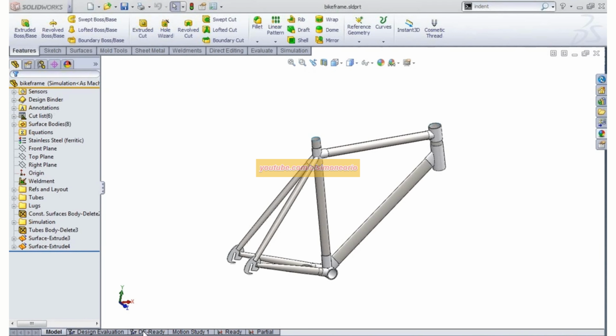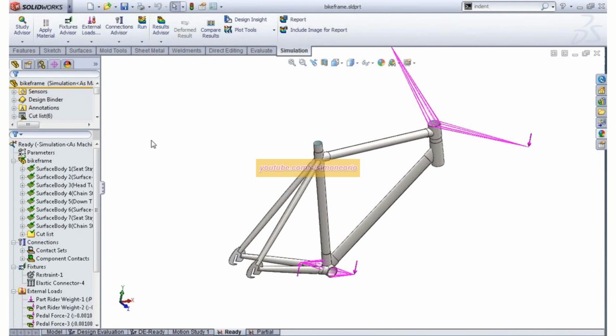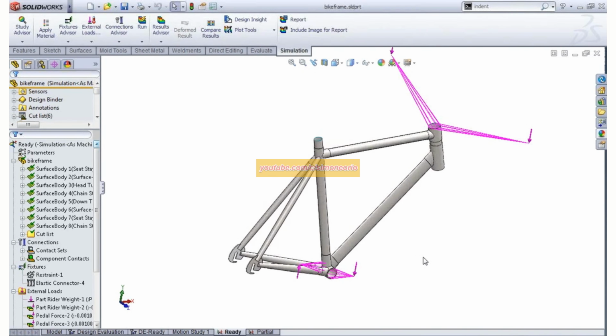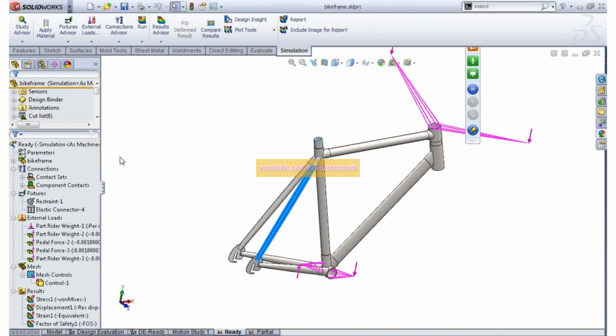So you can see I have the different tabs here at the bottom of the screen. I've set up a stress analysis, and the way we've set this up is a weldment in SOLIDWORKS with some surface bodies as well, just of the frame, and we didn't model the bicyclist, the handlebar, the pedals or anything like that. We're just interested in optimizing the frame because we're purchasing those other components. We don't really have control of them. So we've even gone ahead and set up our analysis. It understood the welded members and the surface bodies automatically because the simulation picks up on that.